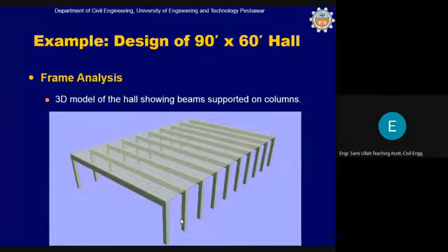There will be walls in this case also, but the walls will be partition walls only. There will be partition walls between these two columns. So the walls will not take part in the load transfer mechanism. These will be just non-load bearing walls, transferring no load except their own load to the ground. When I say do not transfer, I mean they will not transfer any load from the structural system to the ground. Okay, the load path in this case will be like this.